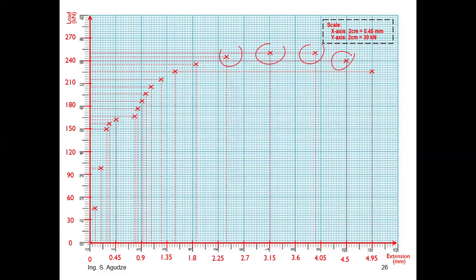Okay. Now, this is a mild steel bar. So typically, for the stress strain graph, up to a certain point, it will be a straight line. So you put your rule on it from the origin up to a certain point, say somewhere here, a straight line, and then the remaining becomes a smooth curve all the way to the end. And that one you have to do, and then you get something like this. Beautiful. Okay, so this makes plotting so simple and so easy.